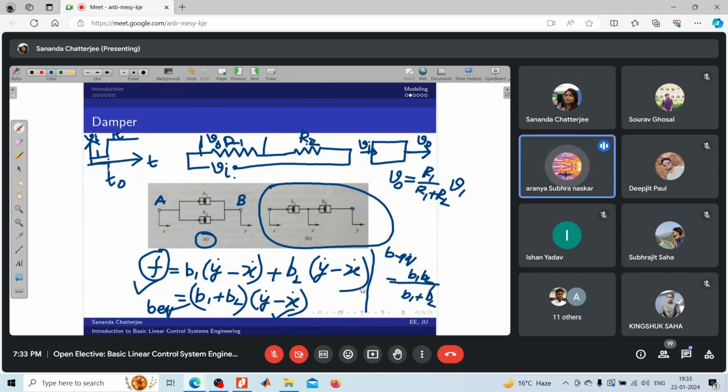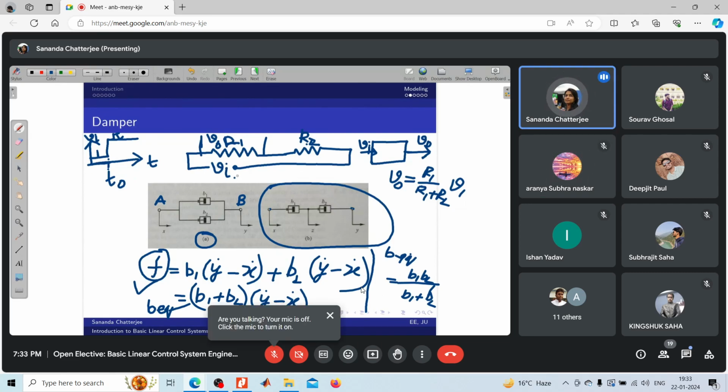Series and parallel cases are just interchanged. Yes. So this holds for resistance also. If we take resistance in series, this will be similar to the damper in parallel, and this will be similar to resistance in series. So whatever the connection, if we take an element which is static in nature, and combine multiple of that element in any combination, we will get some equivalent value.